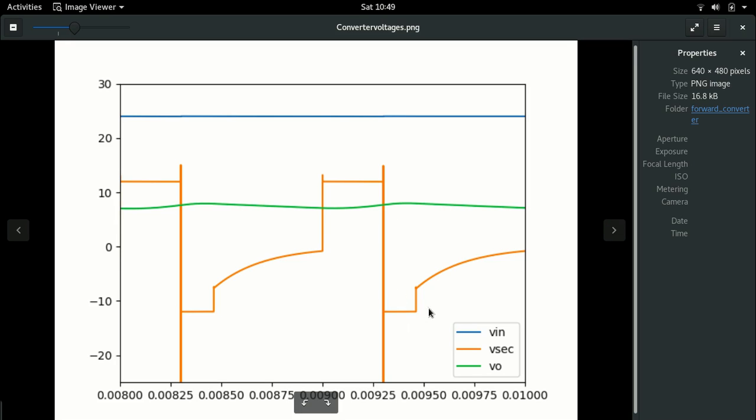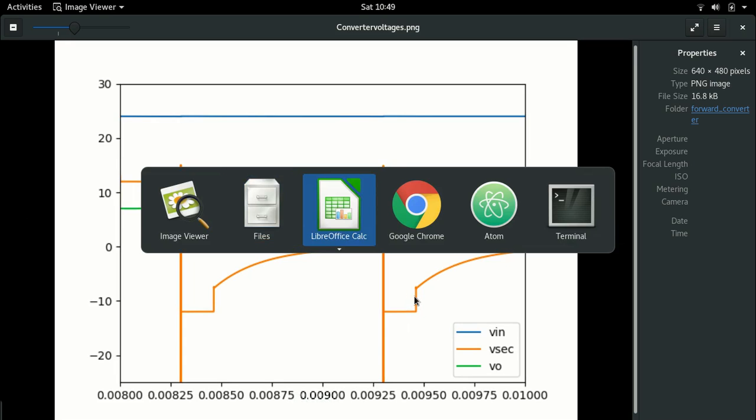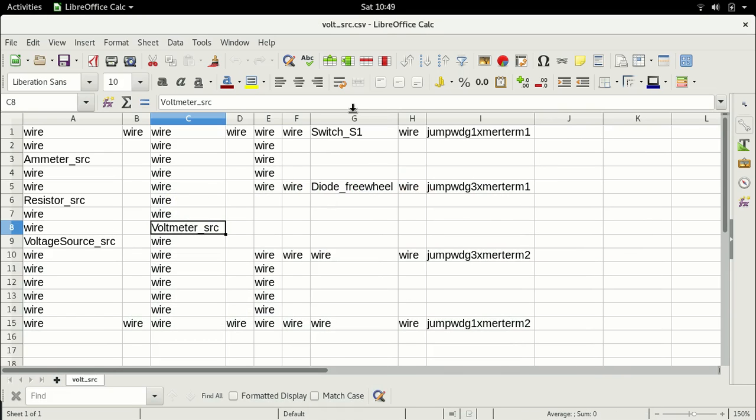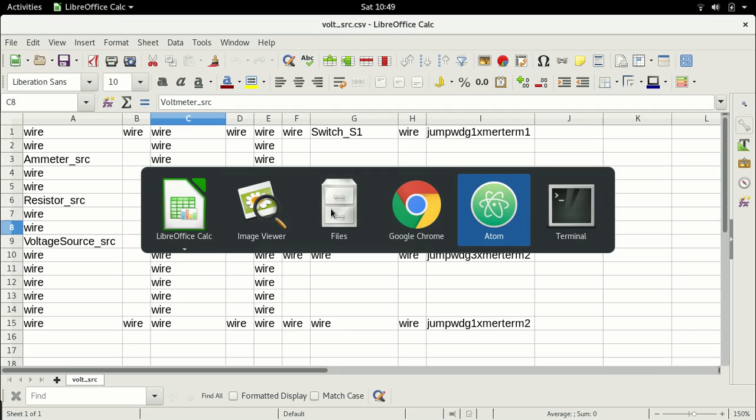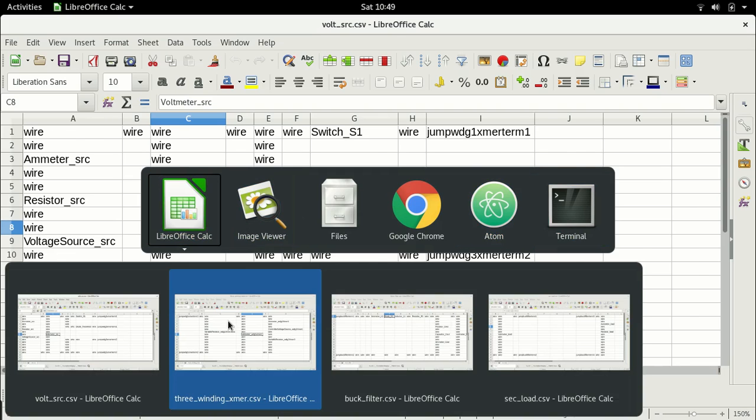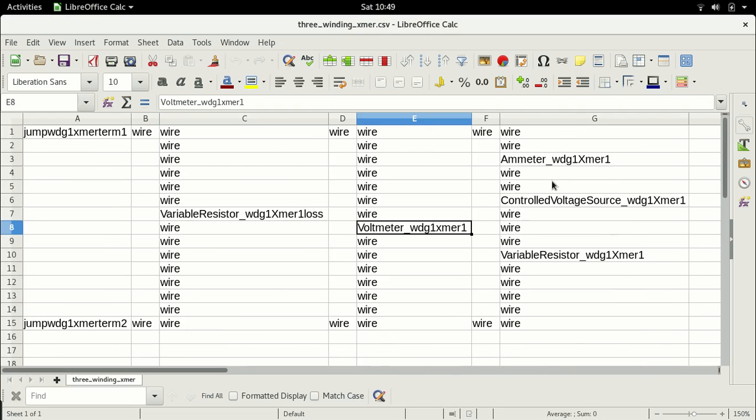Now the question is, why is that so? Let's have a look. Once the switch is closed, winding 1 does not have any voltage at all, at least from this source. But remember, the idea behind this 3-winding transformer is that you do not want to disrupt the magnetic field or the magnetizing current in the transformer, which means the current has to continue to flow.